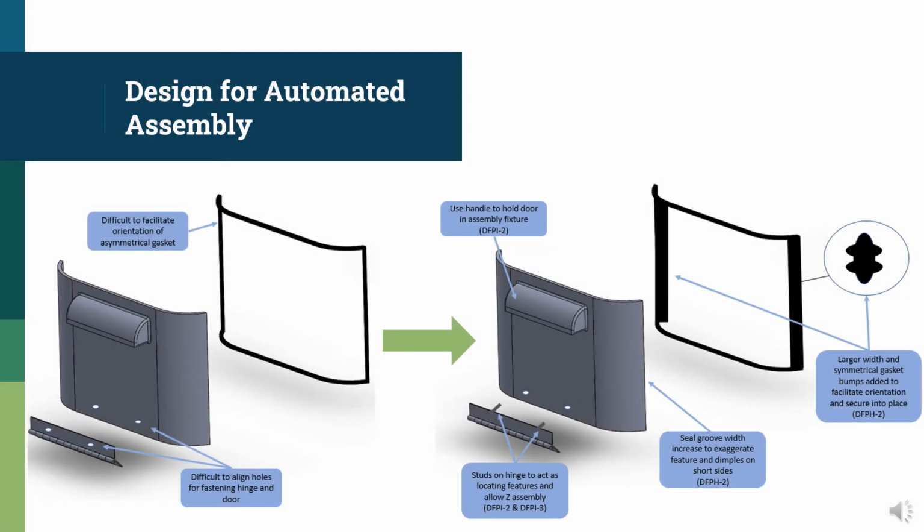We redesigned the door subassembly to allow for automated assembly. Initially, it was difficult to align the holes for fastening the hinge in the door, and so we changed it to studs on the hinge to act as locating features and allow for Z-assembly.